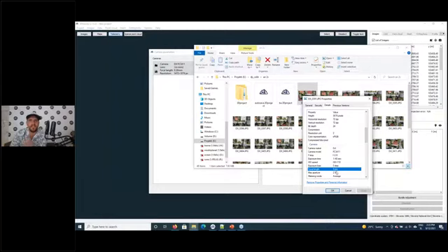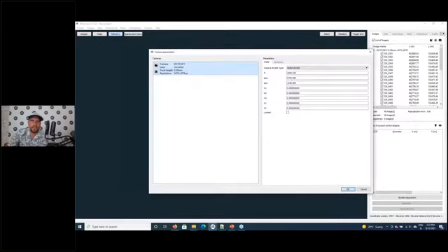This value is not very accurate. So from this value and from additional information inside, we calculated the initial focal length to be approximately 3,400 pixels. The principal point we place by default in the center of the image, and the rest of the parameters we set to 0. And by default, the parameters are already unlocked.